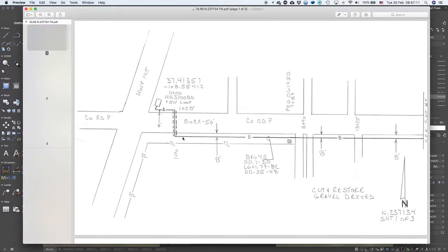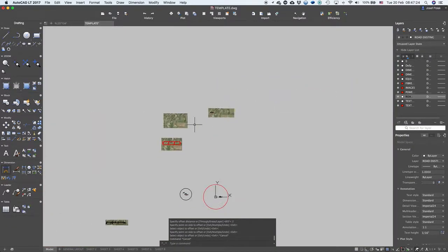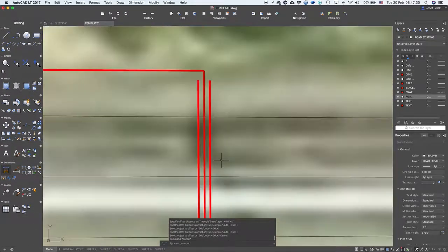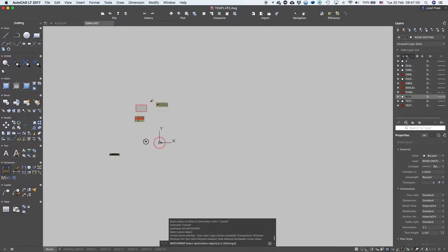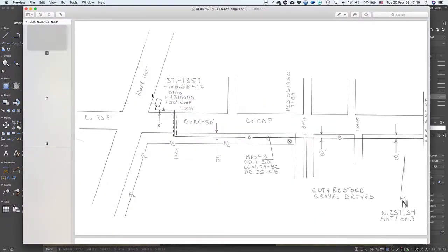To specify the bore, we use a dash line on the edge. Again, simple as that. I just do offset 1 foot. Just keep it standard. Everybody who is doing these drawings keeps the same standard, and it's dashed. So again, no need to think about it. Just match the properties of any bore which you have in the drawing. And that's it.